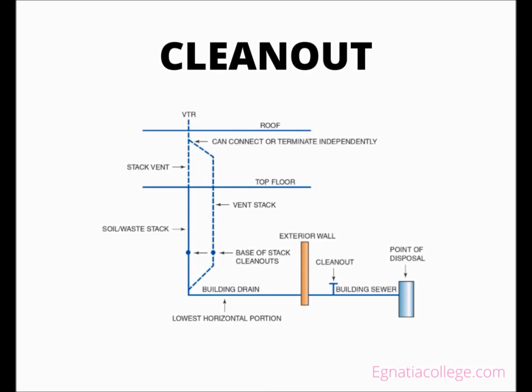Exterior cleanouts in a sidewalk or driveway must be installed flush with the finished grade and must be designed to handle relevant traffic loads. Vertical piping has a DWV fitting known as a test tee or a wall cleanout. The test tee is also used to perform a water test on the system during the installation phase of construction.